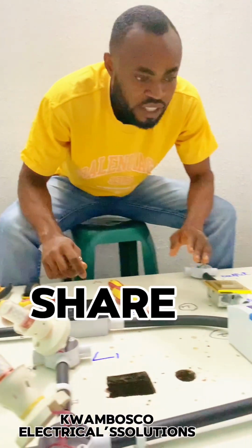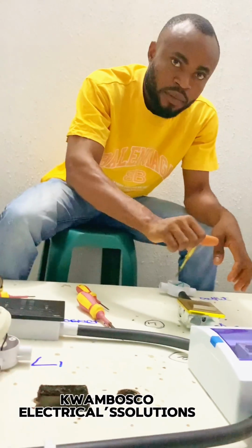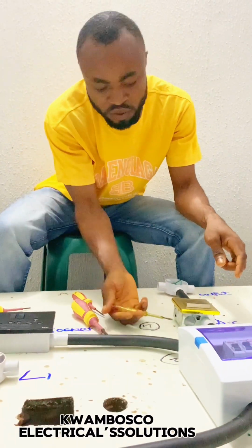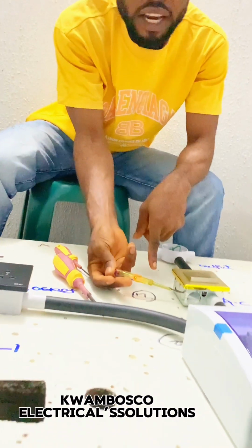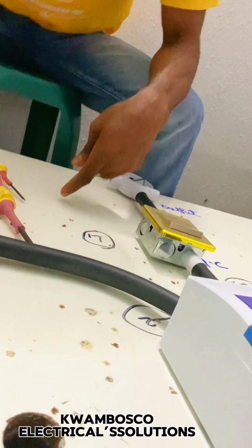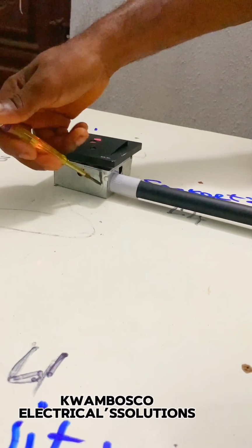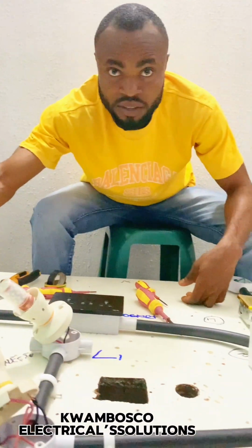So most of the time, the thing that causes this is when you are screwing, your screw is one of the things that causes this leakage. Look at it. Now, this knockout box is showing light, which is not supposed to be like this. If you look this side also, there's light, and it's not supposed to be like this. That means the head has light, and it's very dangerous.